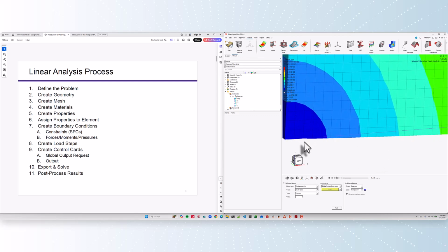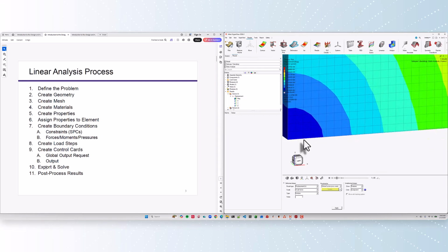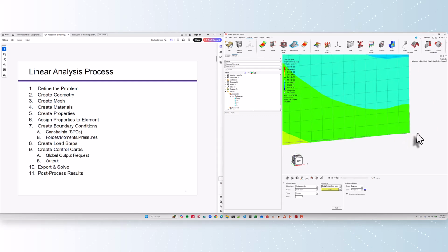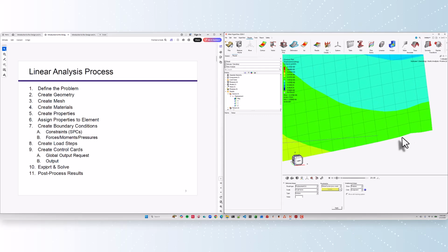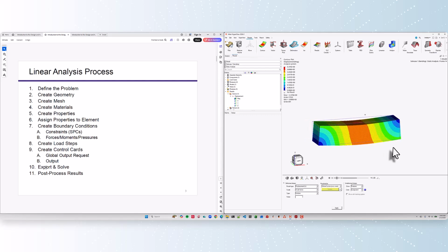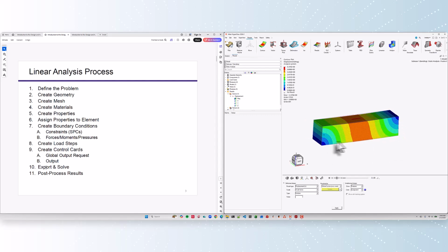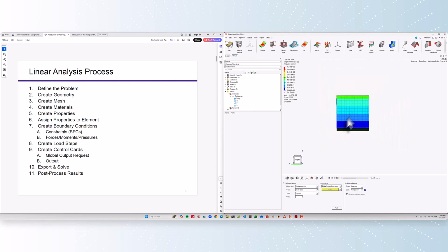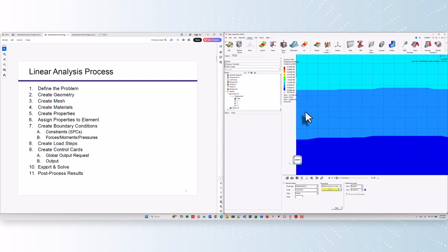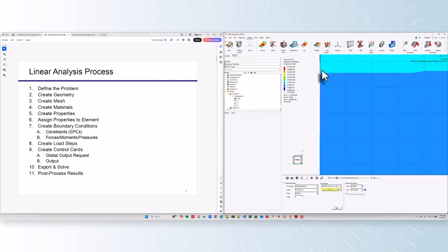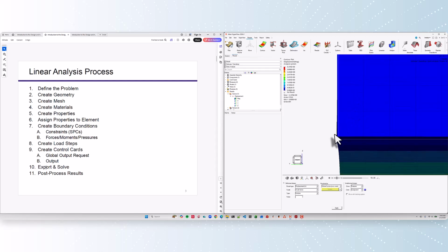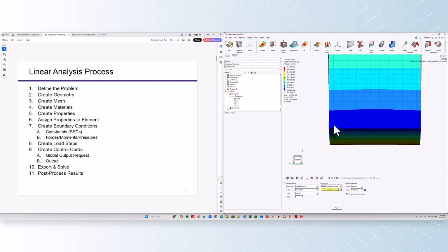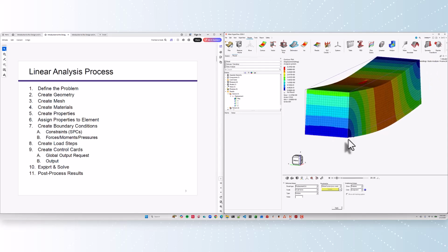So I can see indeed it's sitting on this roller and this roller is not moving in X. But if you look at this one, you can see that roller is moving in X, which is exactly what I want, right? I want it to freely move, but be resisted in Z completely. And you can also see, if I were to look at that in the Y direction, that it's allowed to come in, or actually in this case, it goes out in the top a little bit, and it should come in. It goes out in the bottom too. So it's freely allowed to move, which is exactly what I was talking about.